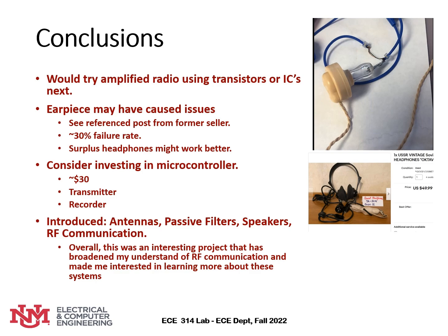After finishing this, I did some research into these earpieces. They're really popular online, and it turns out that there's like a 30% failure rate to them, due to one of the contacts in it being made of aluminum and just being glued on with non-conductive glue. Some surplus headphones might work better, although they're expensive. These are $50, and they only get more expensive from there.